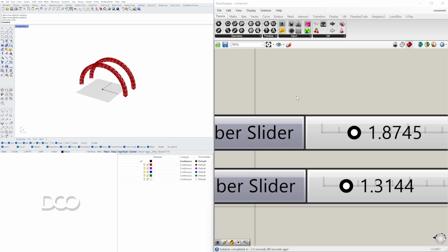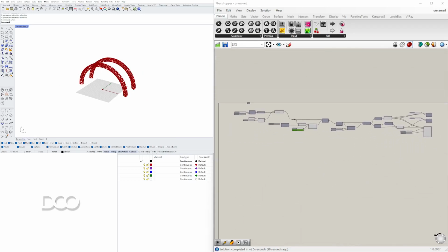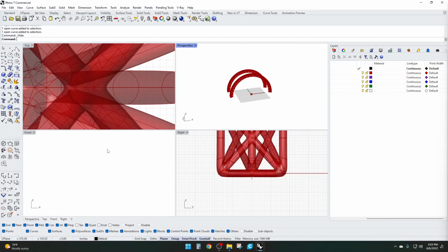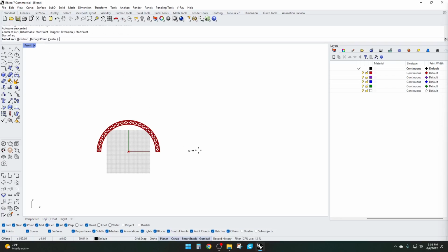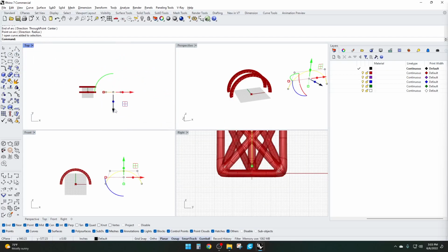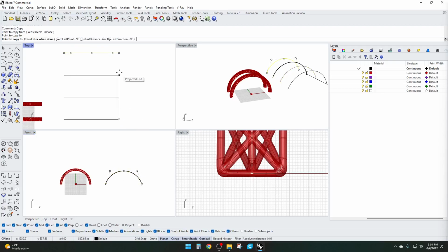Cool. So we've done this mostly parametric here. What I will be doing now is let's go here in Rhino and let's create a set of arcs that are more dynamic. So I'll just create a basic arc here, starting here, ending here, direction this way. Then under the top view, I'll create copy, and I'll create more than one copy. So I'll do copy, turn on project, so we don't move it up or down.